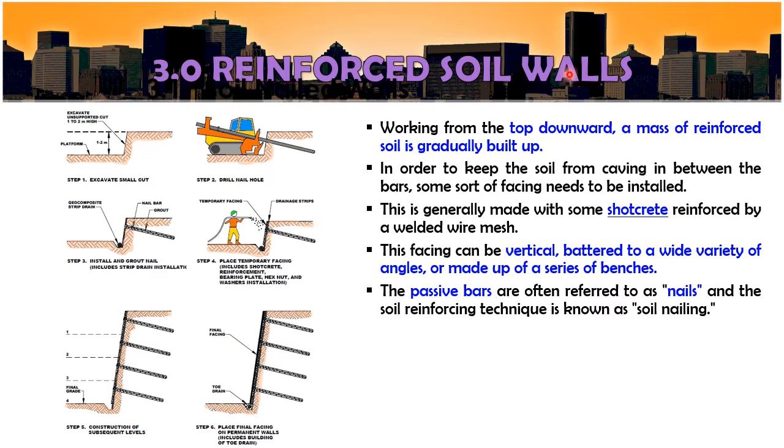The construction of reinforced soil walls includes: the soil is first excavated, depending on the ability of the cut face to remain vertical without support. Holes are drilled along the cut. Jadi dia akan berlubang lah tanah ni ya. Threaded steel bars are inserted in the hole. The length of the bar is a function of the soil type, but it is approximately half the final depth of excavation. The bars will protrude a few inches out of the hole. So, bar ni akan terkeluar sikit lah, beberapa inch.